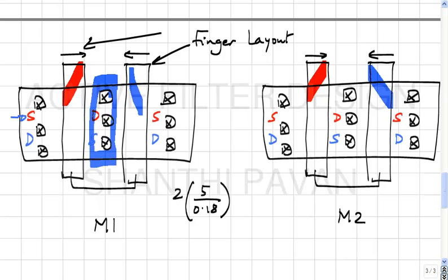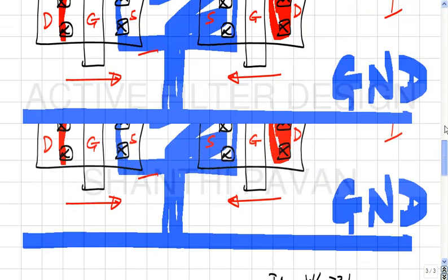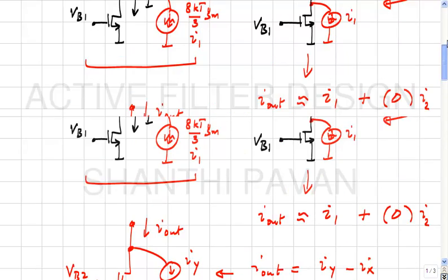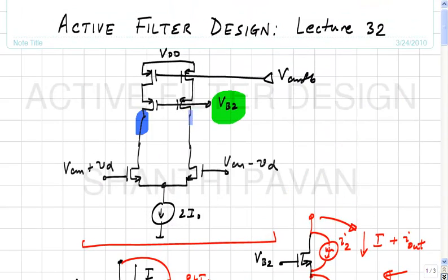Correct? You understand? So especially in our situation where we are sensitive to parasitics, ideally we want the parasitic capacitance that appears at those nodes to be as small or as large as possible. As small as possible. Why? I mean, all that will add to the integrating capacitance.